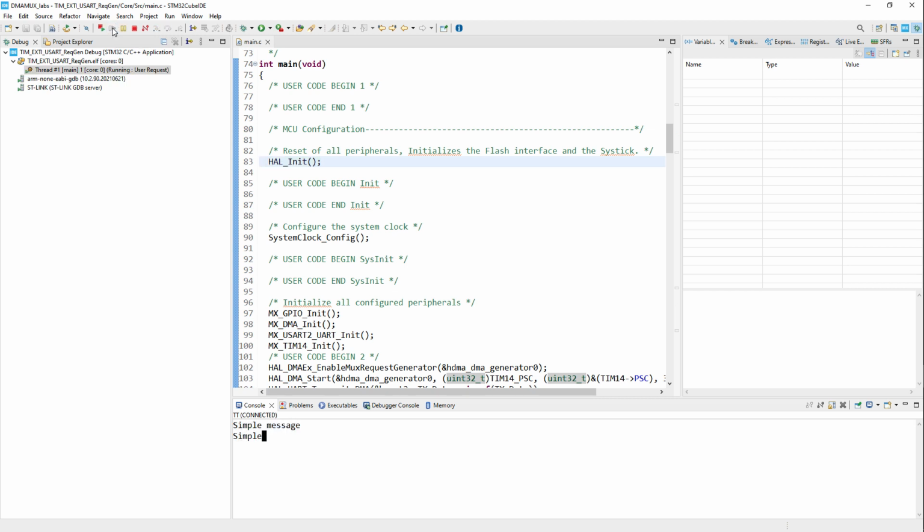And I can see that the simple message string is displaying, and I will press the blue button. And as you can see, the speed is changing on each button press. Now is the fastest one, the prescaler has the lowest number. Now I'm changing once again, so from this 3000 we are landing to 12,000 for inside the prescaler, and I'm changing right now for the middle value and again for the fast one.